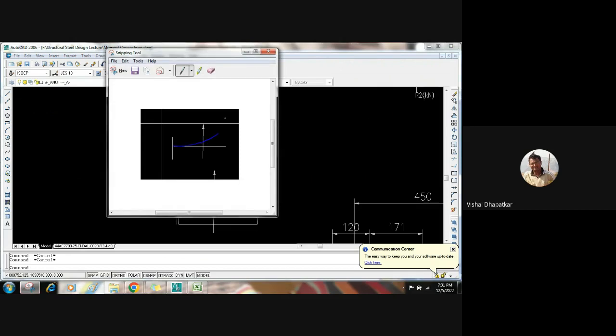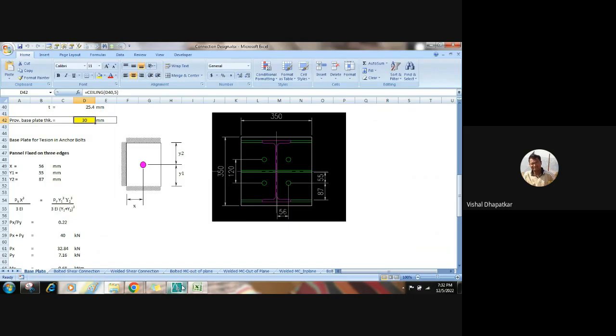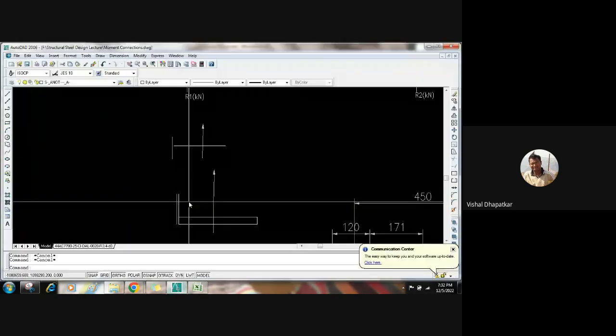When it is lifting the plate. Since this is the fixed end and this is the free end, because of the tension in the bolt, the deflection will be like this. So this is for the cantilever portion, this much of portion, and the other case will be for the load acting at an intermediate level.